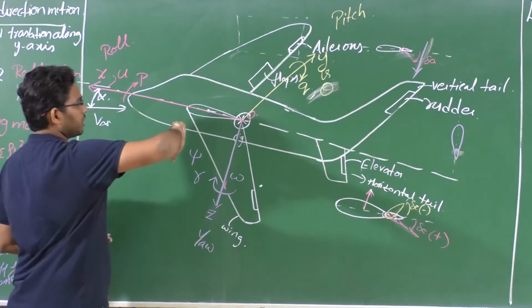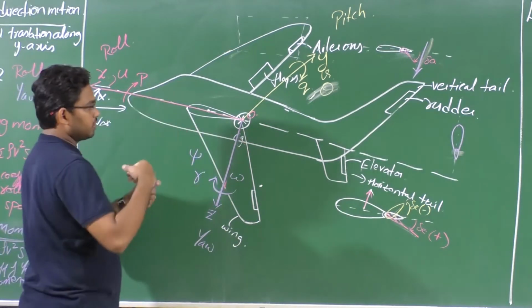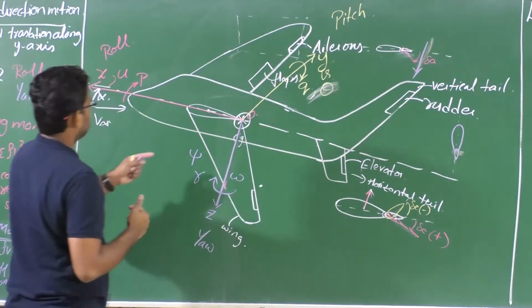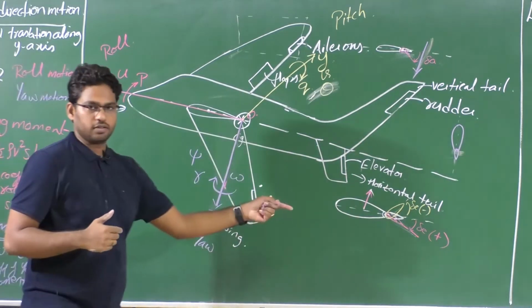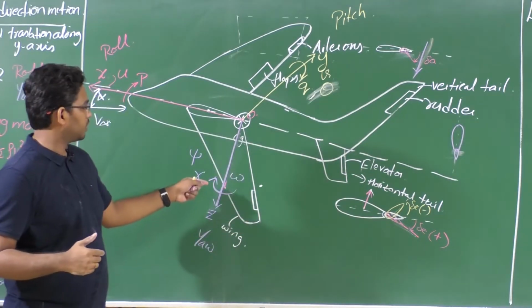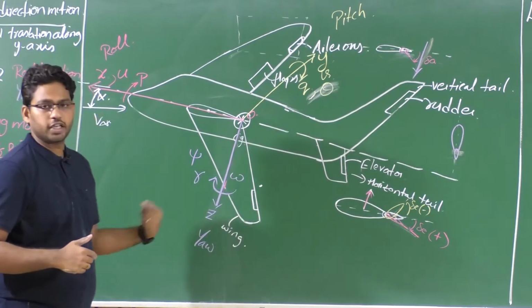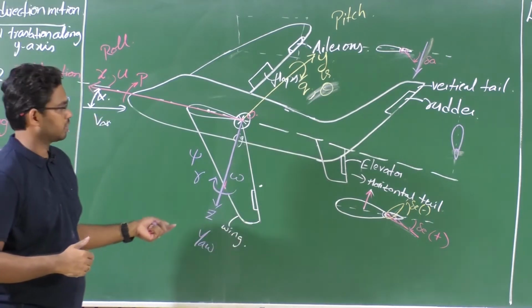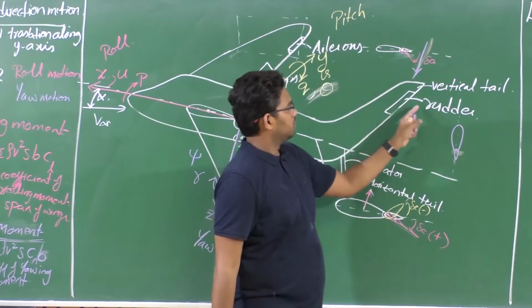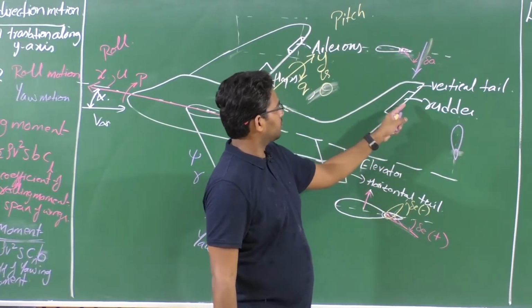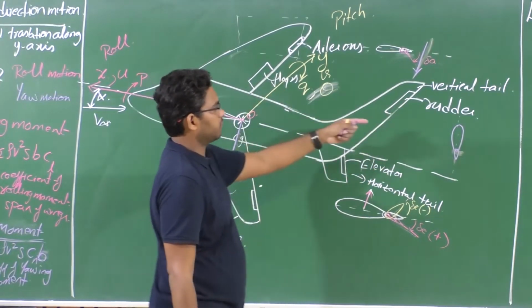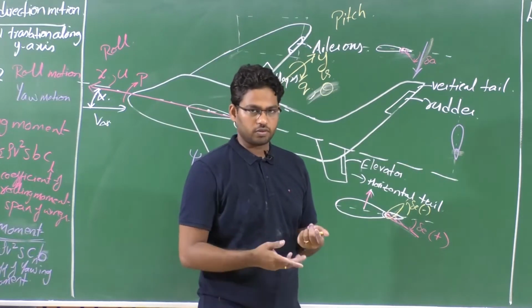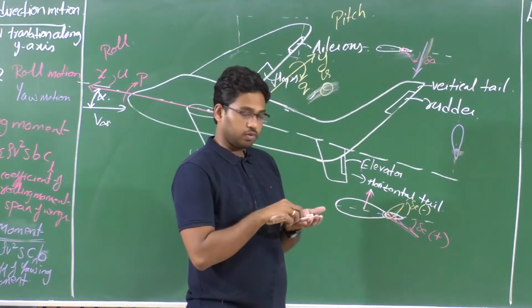So that yawing moment is negative, right? It is rotating the left wing back. So the yawing moment that rotates the left wing back is the negative yawing moment. That's what we just discussed. So when the rudder deflection is producing a negative yawing moment, the corresponding deflection of that rudder is considered to be positive, right?